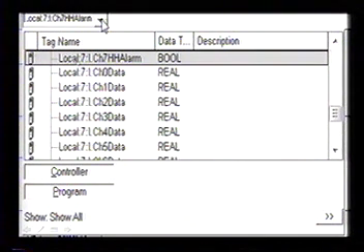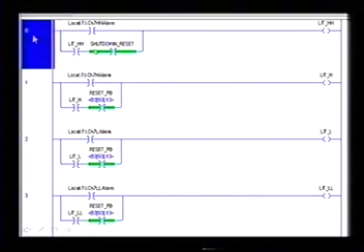And then I showed you the tag monitor and how you can actually look at these values. You can see the high alarm is a Boolean value. The channel 0 data is a real value. And then here's a sample code. You can see I took the high alarm and I tied it to an alarm high, and it's got a shutdown reset. Because remember, the LSHH was a shutdown. So here we have just a reset. It's just an alarm. It's a high value. It's an LAH.